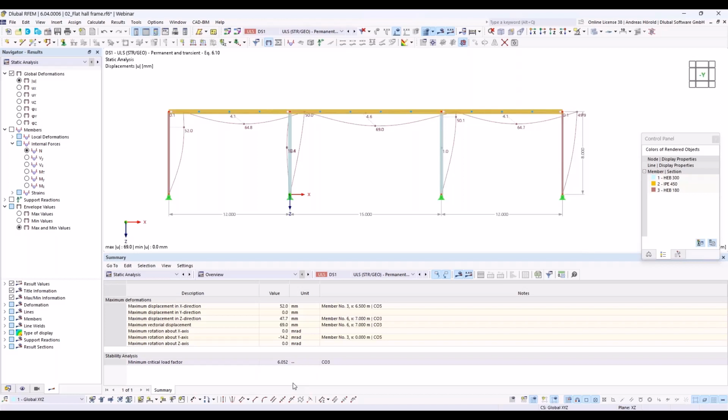But as I already mentioned, for the stability design using the classic equivalent bar method, meaning method C, the internal forces can be calculated according to geometrical linear analysis, and buckling lengths must be assigned to the columns. But for the design of the lateral torsional buckling, the application of the second order analysis is also required with this method.